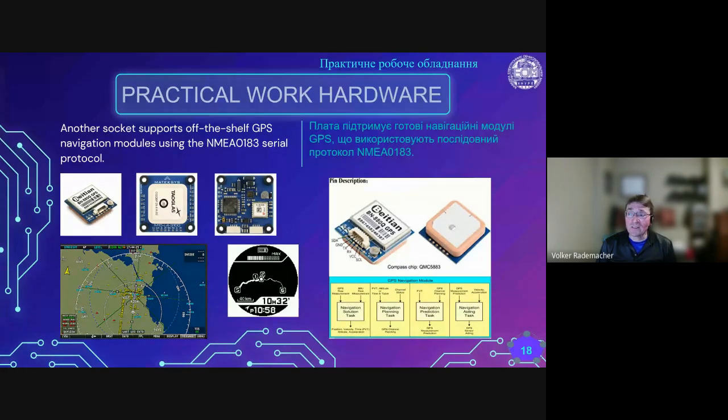The socket is somewhat universal. It will fit several different GPS modules for experimentation, including devices with the u-blox Neo 6M, 8M chipset, the Chinese ATGM 336, the Quectel L86 chipsets. Some of these modules are GPS only, some are GLONASS. In the description of the NMEA sentences, that's what the text strings are called, an NMEA sentence is basically just a text string,